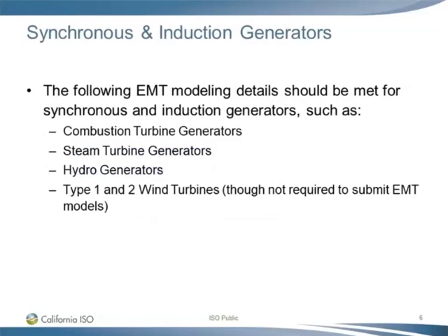So next we'll be going over EMT modeling requirements for synchronous and induction generators. The EMT modeling details that are discussed in the next slide should be met for synchronous and induction generators, which include combustion turbine generators, steam turbine generators, hydro generators, and type 1 and 2 wind turbines. Although type 1 and type 2 are not required to submit EMT models. Next slide, please.